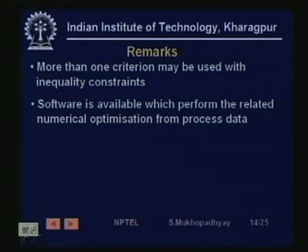In many cases, your criteria may be stated in terms of inequalities, so you actually have a feasible region in which you can operate. When you have complex processes and complex performance criteria, the calculation of the gain may require large amounts of numerical trial and error, or using sophisticated optimization algorithms which search for a good value of the parameters over some feasible space. Therefore you need software, and various kinds of tuning software are actually sold by the manufacturers.